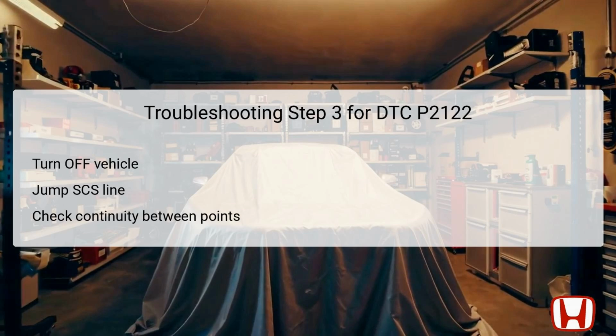Conducting this test when the vehicle is off helps prevent any risk of electrical interference or shorting. If continuity is confirmed, it indicates a short in the AP1 wire that must be repaired to restore normal function. If not, you can confidently move to the next step in troubleshooting.